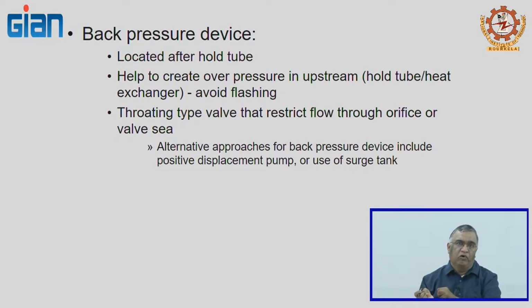If you do not have the back pressure valve, it is going to start flashing or becoming like steam, and that can create a lot of problems.